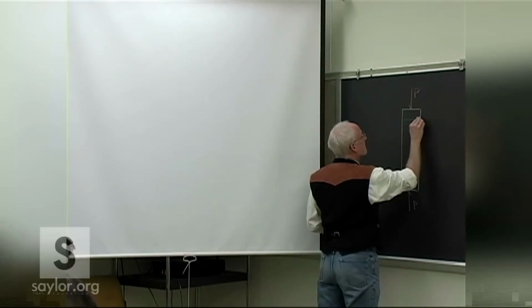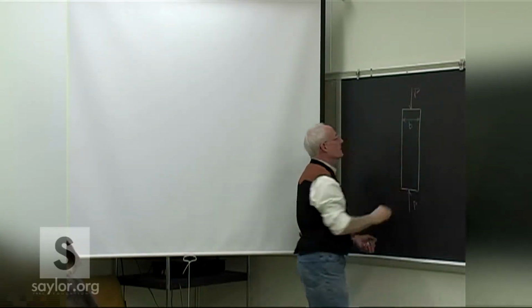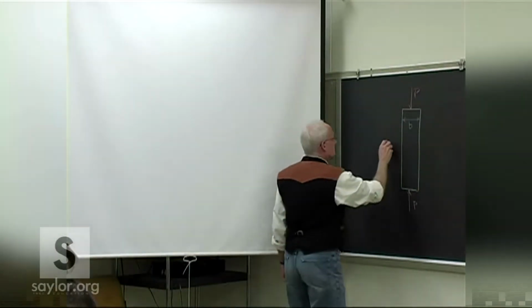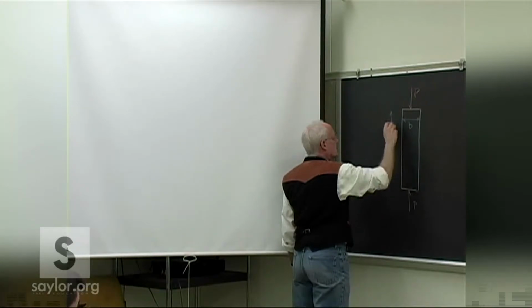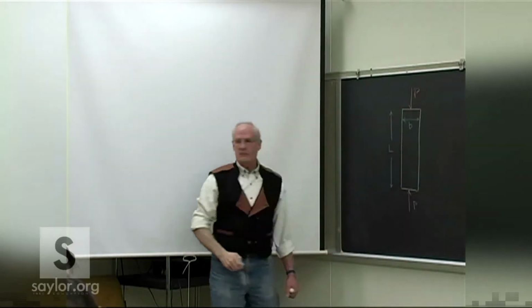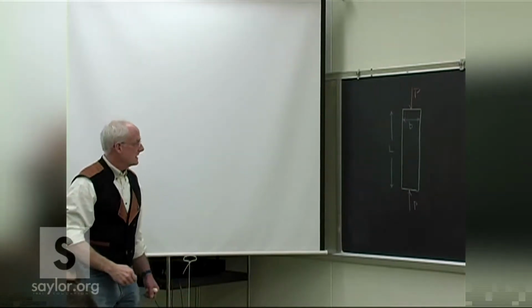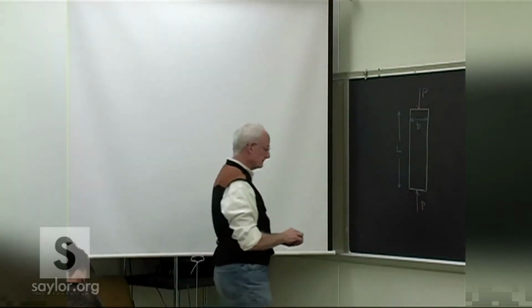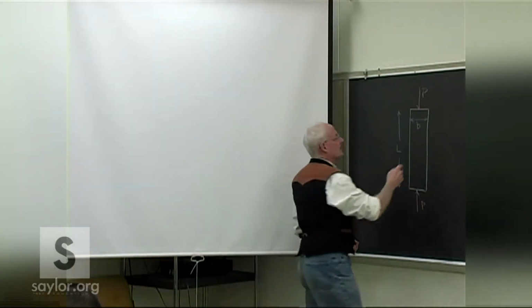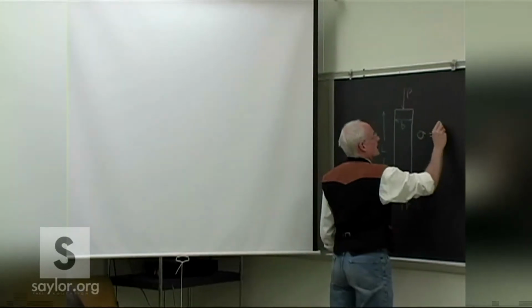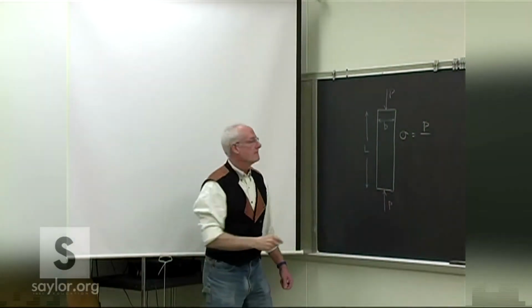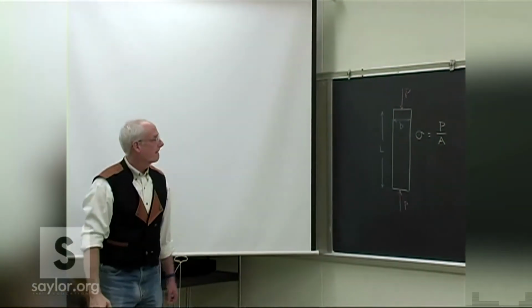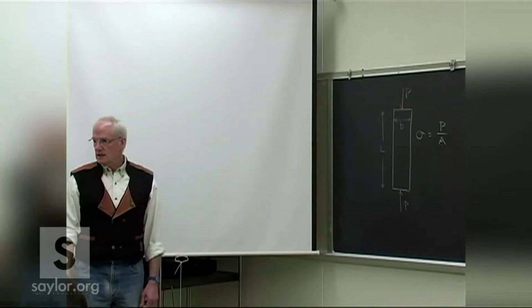So imagine we've got a part here that's of width B, which is very much less than its length L. So we've looked at lots of these kind of pieces before. In fact, this is the situation that defines our axial loading. And we've figured out the stress by simply taking that total load, dividing the cross-sectional area into that load, and we get the anticipated stress.